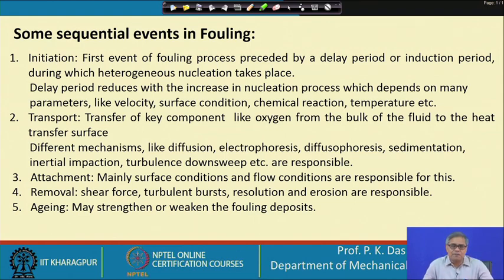That does not take place immediately when you start operating a brand new heat exchanger; it takes a certain time. So, that is the delay time. After that there is transport. Transport is the transfer of a key component like oxygen from the bulk fluid to the heat transfer surface. Okay. So, this is transport. There should be some sort of transport.